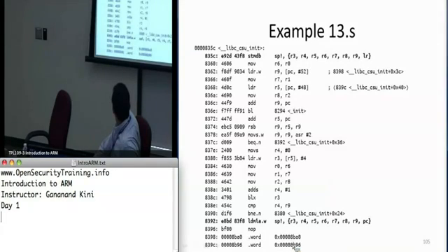Actually, this is a jump table, so it's loading the memory contents up. So it's loading this address. Does that make sense? So it's taking PC plus 52, which is this, the memory contents of this, interesting, and storing that into R9.